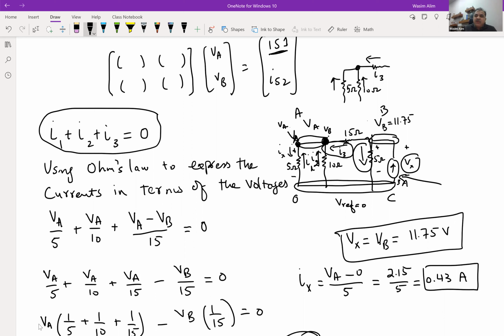So now, if there were three nodes, I would derive three equations, right? Then you will have three equations, three unknowns in that case. So you'll have three voltages to look for. But with the examples we've been working on, we're only working with two voltages, because if you get to three, it's the same process. It's just that you do the substitution more times.